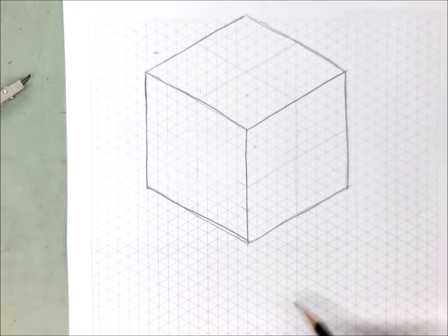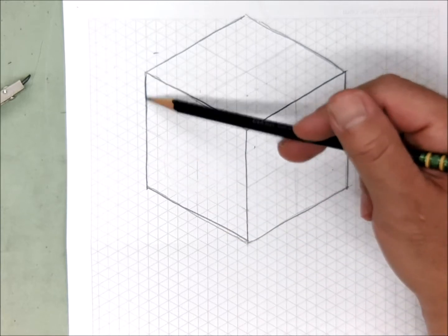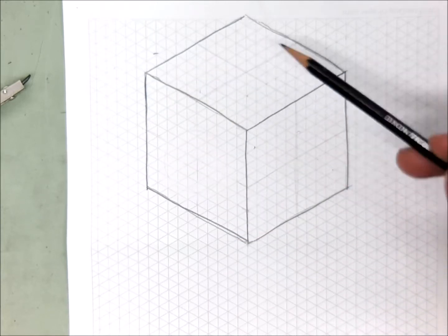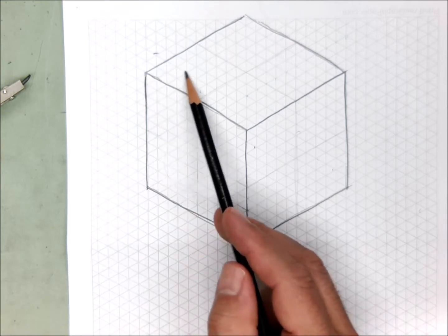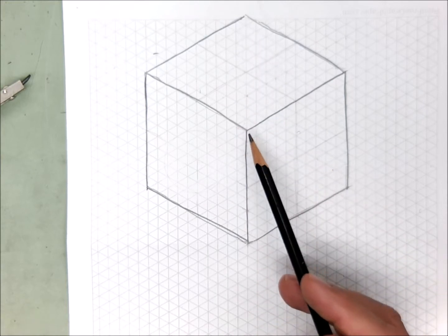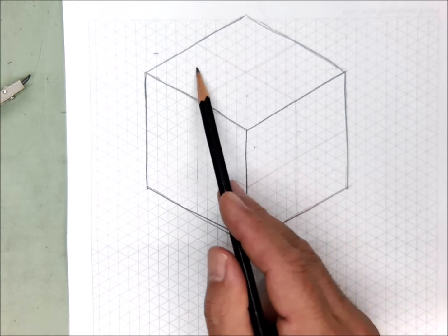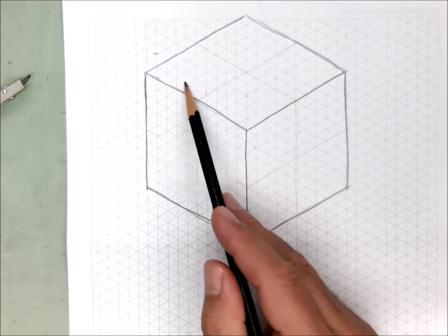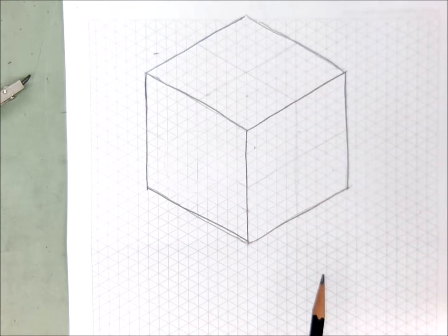Now, keep that in mind, because I want you to look at these surfaces that we made. See, they all look like diamonds, don't they? Here is a diamond, here is a diamond, and here is a diamond. And the way to get things to line up correctly is look at the diamond and look at the long axis of the diamond. So look, this diamond, well, it's long this way, it's shorter this way. If you don't believe me, measure it, or use your dividers to check it, right? So if you can keep that in mind, just remember that the long axis of your ellipse will follow the long axis of the diamond on a cube in that surface.